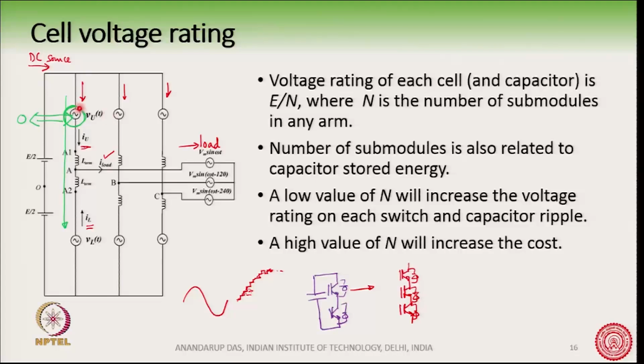These are six single phase voltage sources, and we know that when a single phase current flows through a single phase voltage source with a phase difference between them, the power has a DC component and a second harmonic component.